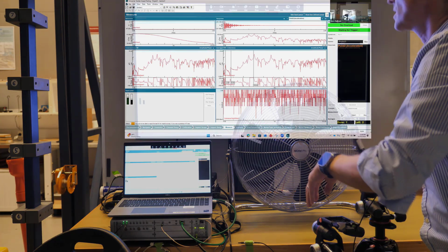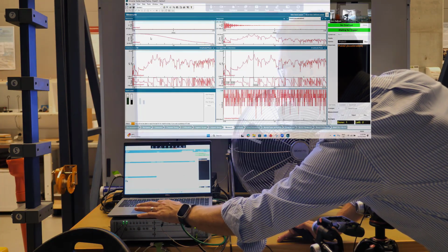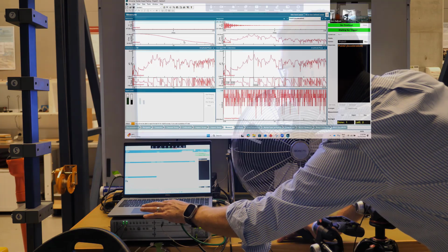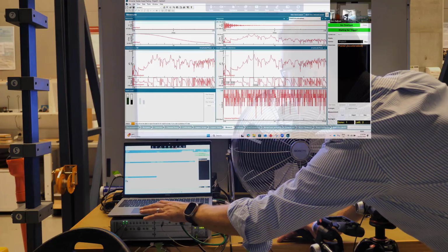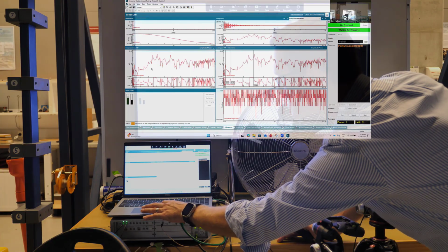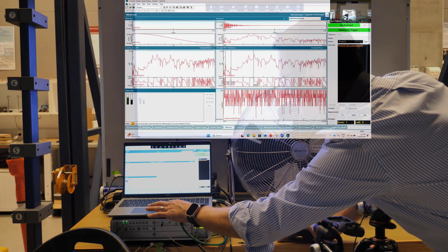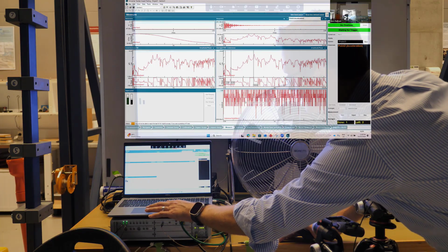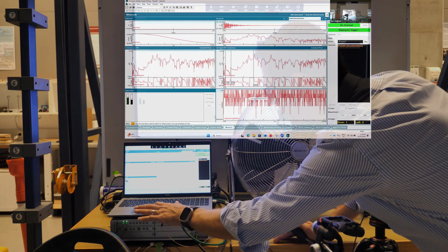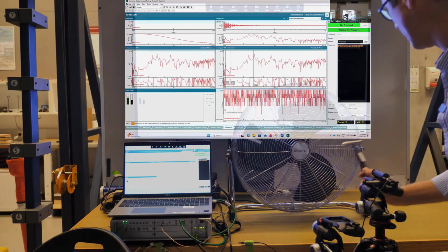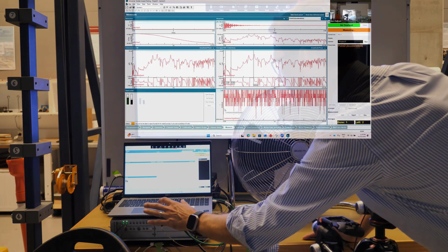And that's a reasonable impact there. You can see the impulse in the top left, the PSD for the impulse, the response top right, and the frequency response PSD, and then the instantaneous FRF here in magnitude and phase, and the average FRF over here, which for the first impact is clearly the same as the instantaneous, and a coherence function which is essentially just 1 across the entire spectrum. I don't see meaningful coherence until I do a second and third impact.